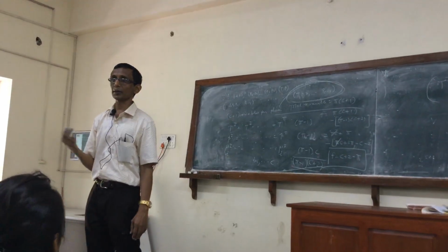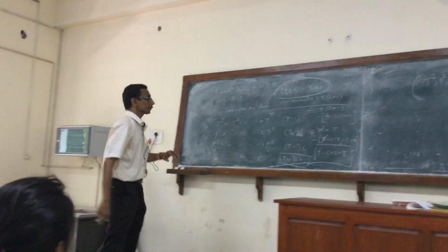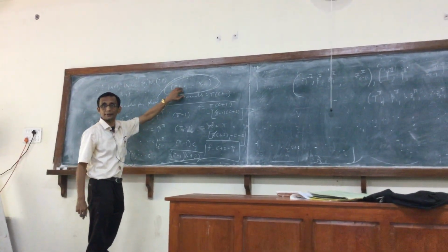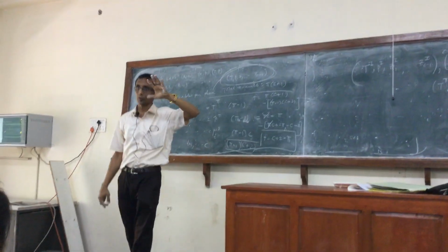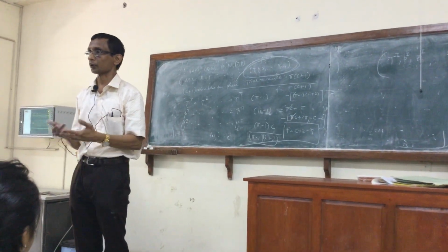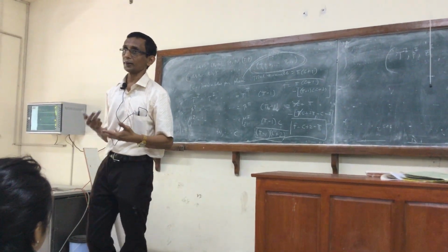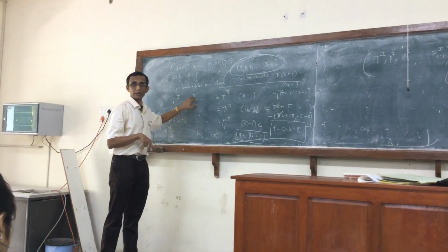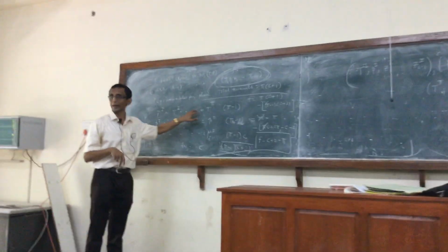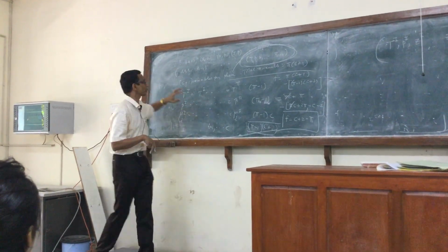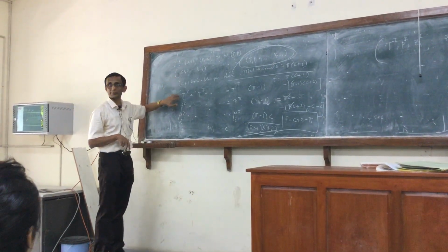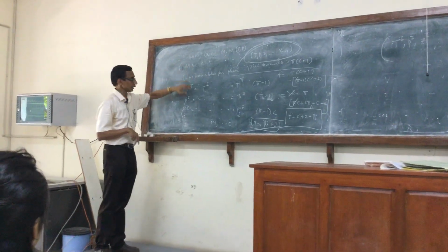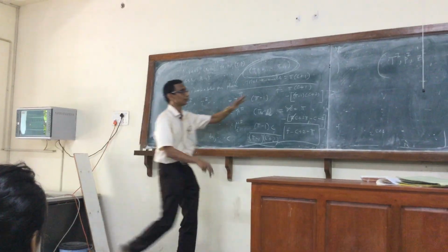However, as we saw in the case of the pure component, this is the most popular choice also. One reason is that the temperature and pressure are easy variables to experimentally control, and so you can plot the phase diagram in terms of those. Another reason is also probably that two of these variables, the temperature and pressure, themselves appear directly in the criterion for equilibrium. If you compare it with this, here I have to express T1 in terms of S, P and the C minus 1 mole fractions. Here that is not required, but they themselves are variables in the set.